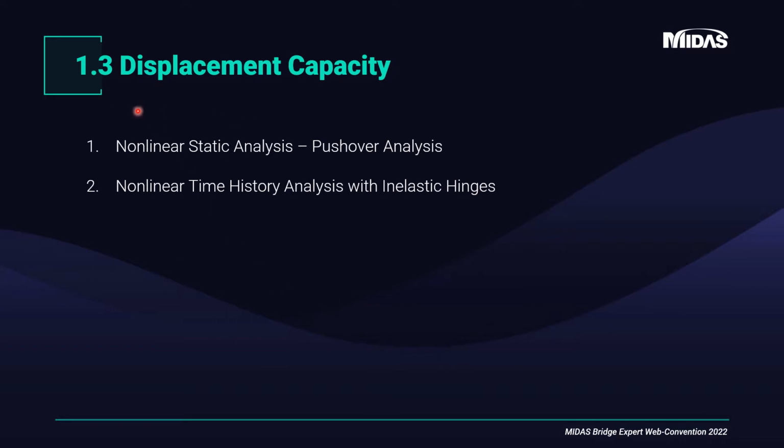Next, for determining the displacement capacity, we can use a non-linear static analysis procedure, which is called pushover analysis, which we'll be looking into in detail in this presentation. The other one is a complete non-linear time history analysis with inelastic hinges.